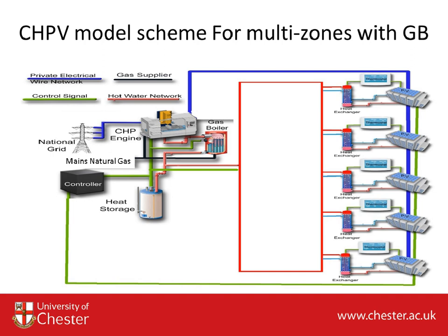And then finally, we got a controller, the big black box, as often called, the brain, and that's got to manage this heat storage, the CHP engine control, when to draw from the grid, and it's got to manage the heat network and the private wire network simultaneously. They're both cross-coupled and interactive, and as Paul mentioned, my aerospace background, my multivariable control expertise certainly comes into play here in understanding the coupling between heat and power.